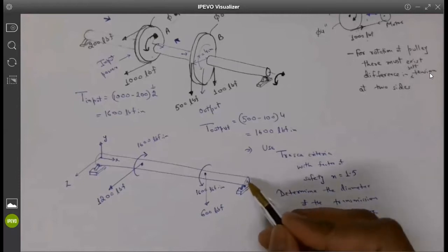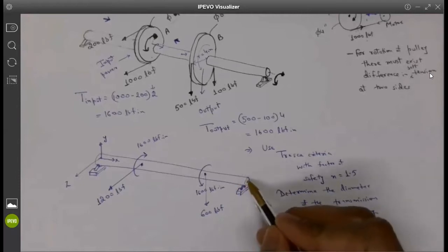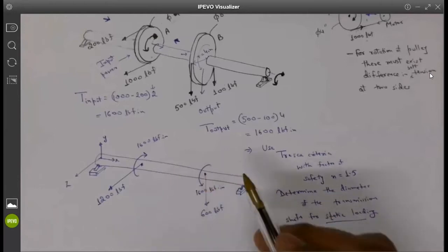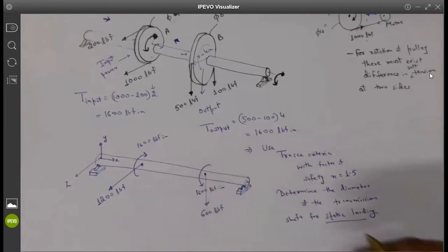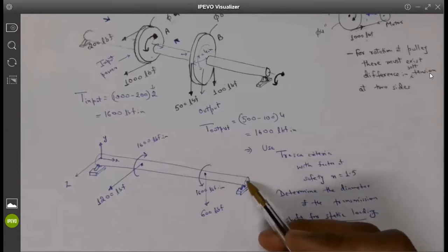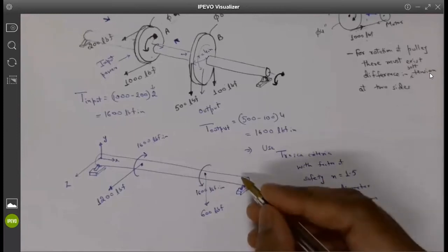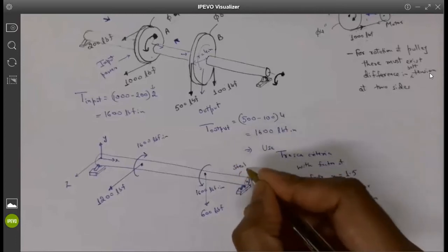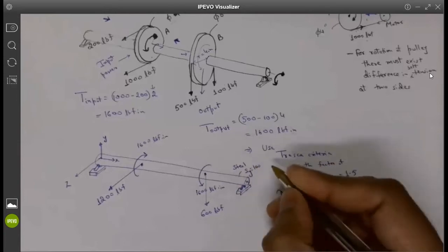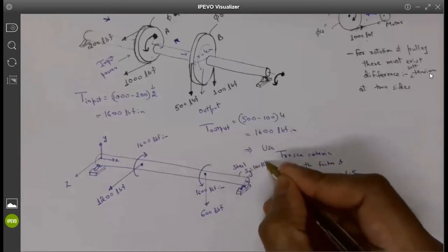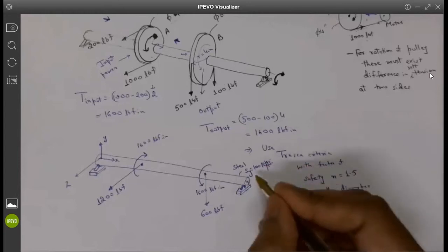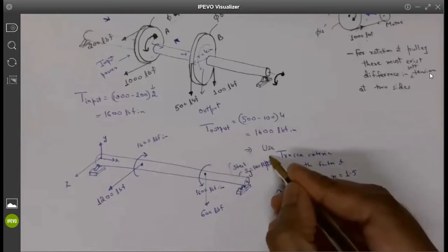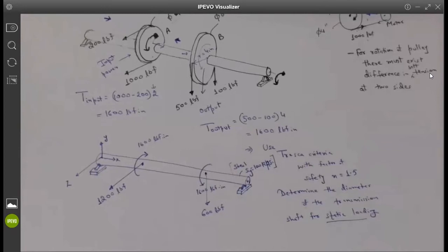At one given instant of time, assuming everything freezes, what are the stresses coming in the material, and how to find the minimum diameter of the shaft with a specific choice of material? Let's say it is steel, and it has a yield strength of 100 kilopounds per square inch, kpsi. So assuming this material, find the specific diameter. Can you help me with what steps I should take?